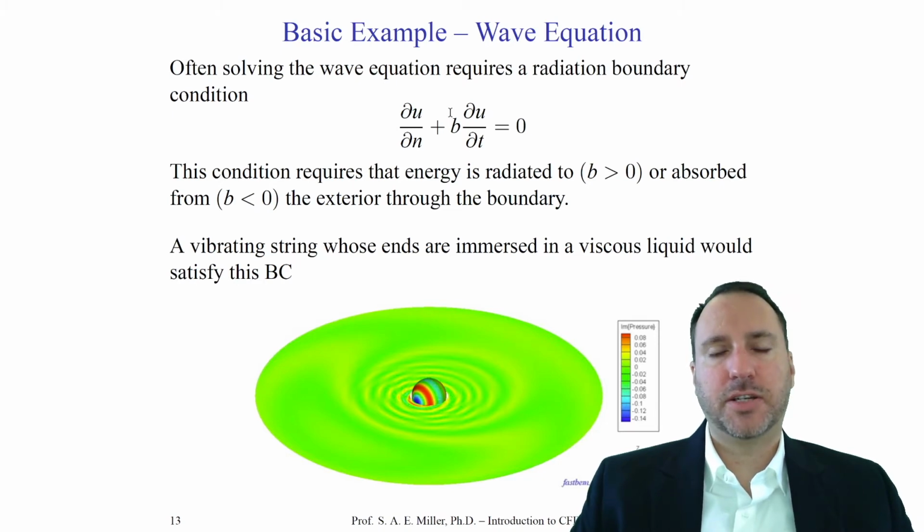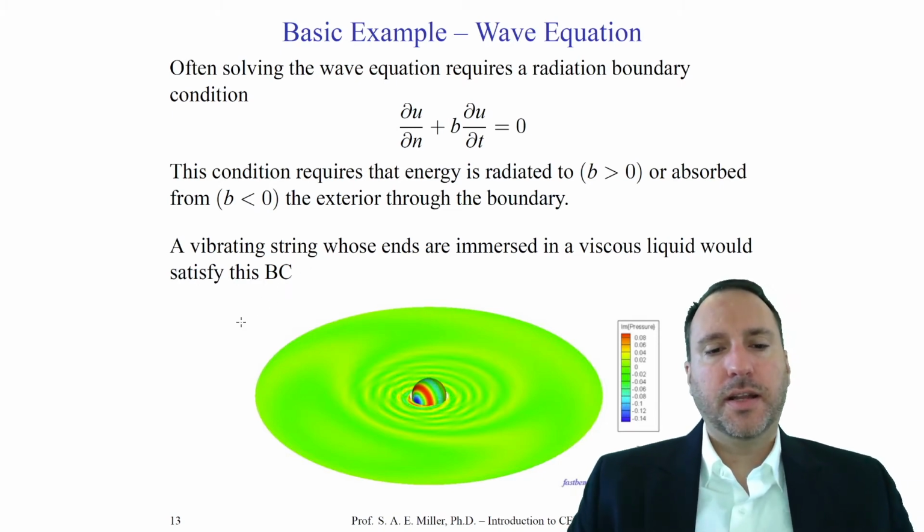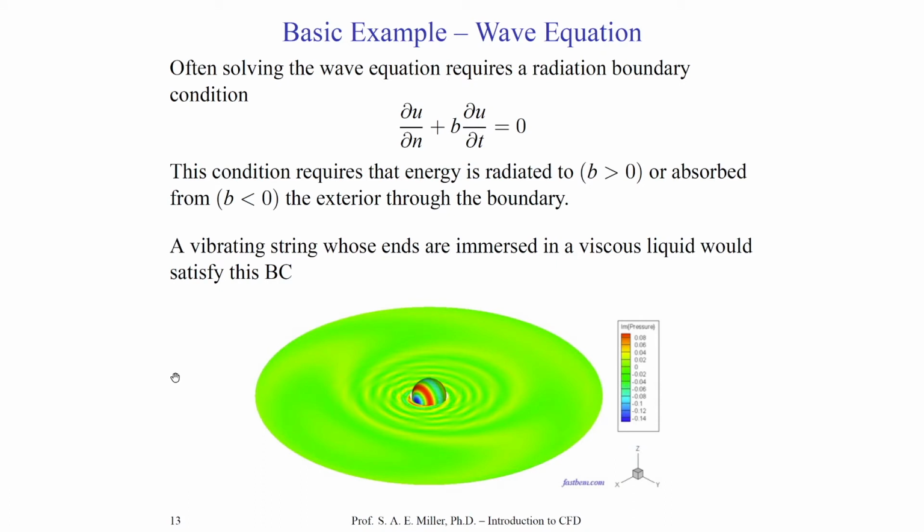In the lower part of the figure, we have shown a particular CFD solution for the complex acoustic pressure, and we're plotting the imaginary part of it. There might be a little sphere embedded in this three-dimensional computational domain. The sphere is a solid surface. It has one particular boundary condition corresponding to a hard wall, perhaps. And then there's a little acoustic source on one side of the sphere.